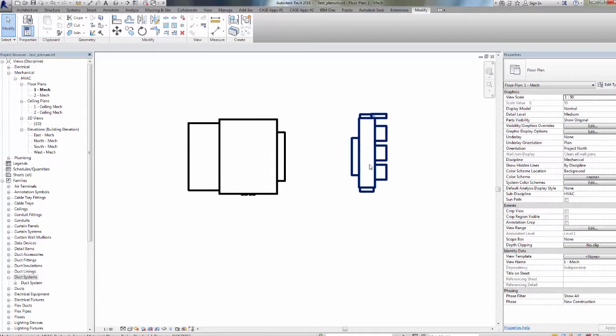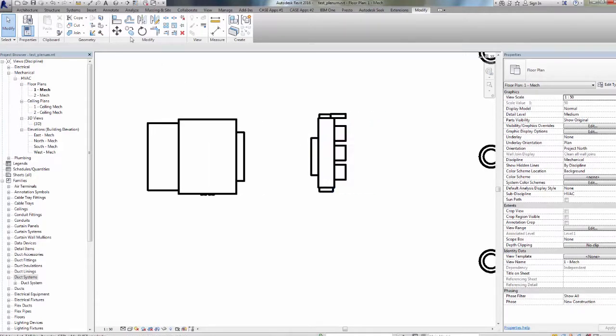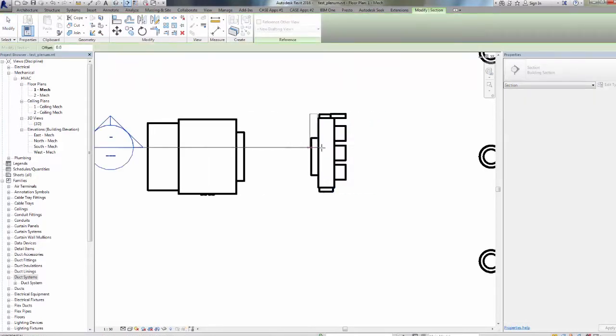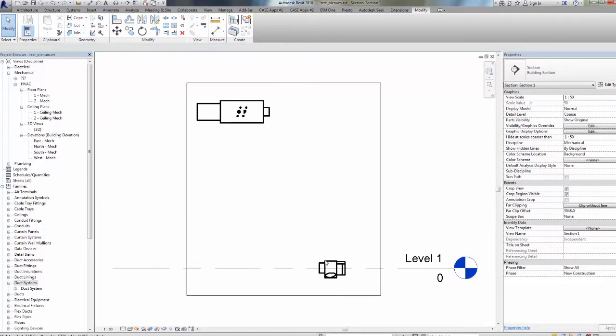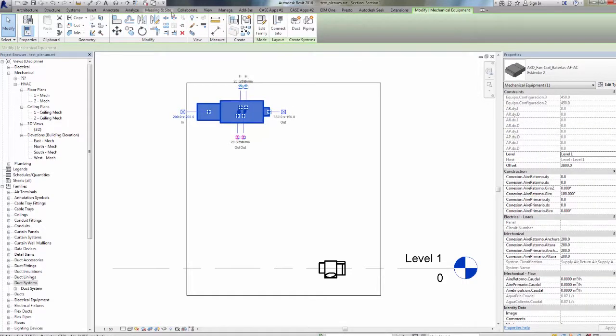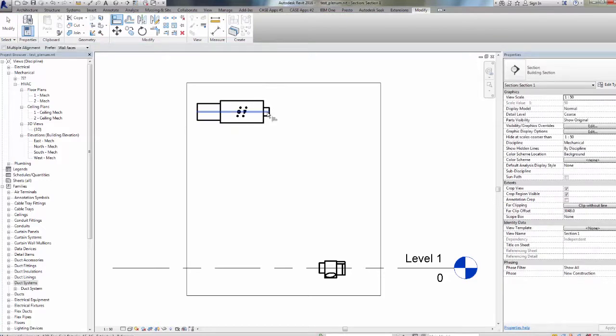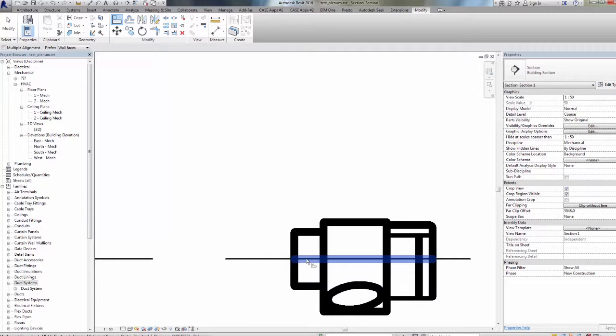Once the plenum is aligned on floor projections, the same is being done in height projection. We are using a section to see that it is not correctly adjusted and to see whether this connector has any plan by means of which the plenum shall be aligned. As well, we see that there are 2 reference plans here, and we must be careful and know that this one is the damper reference plan and this one the neck reference plan.